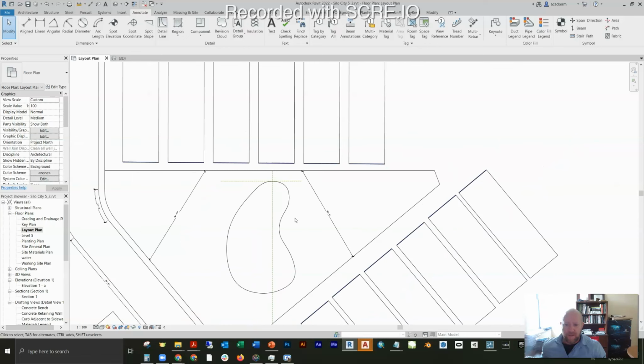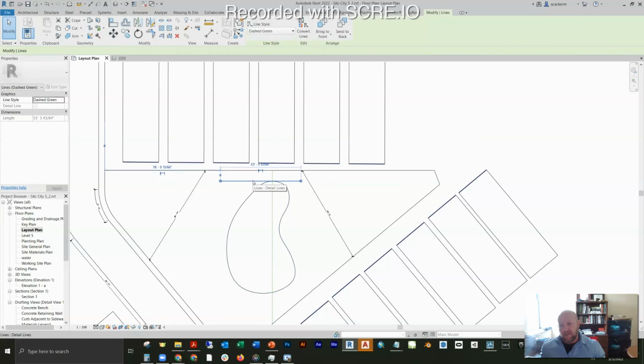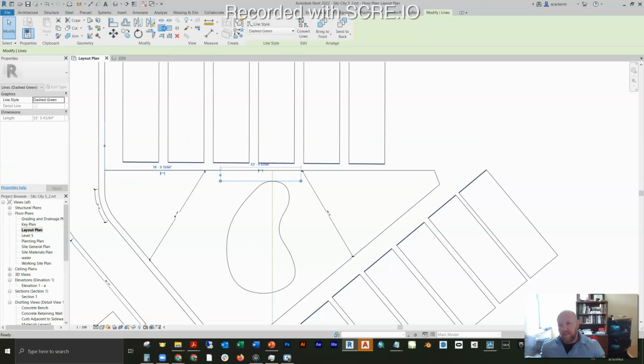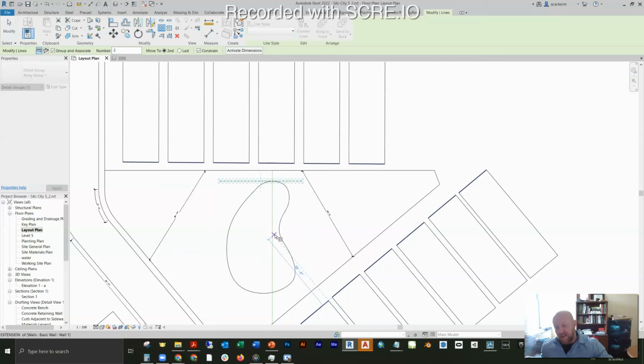Now what I want is to have a series of these lines copied. What this will let me do is establish linear dimensions at established intervals. So I'll click here, and I'm going to array this. I have some choices: I can either click the first and the last point of my array and it'll fill in the rest with even spacing, or I can click my first and my second point with some control over the spacing and it'll array the rest.